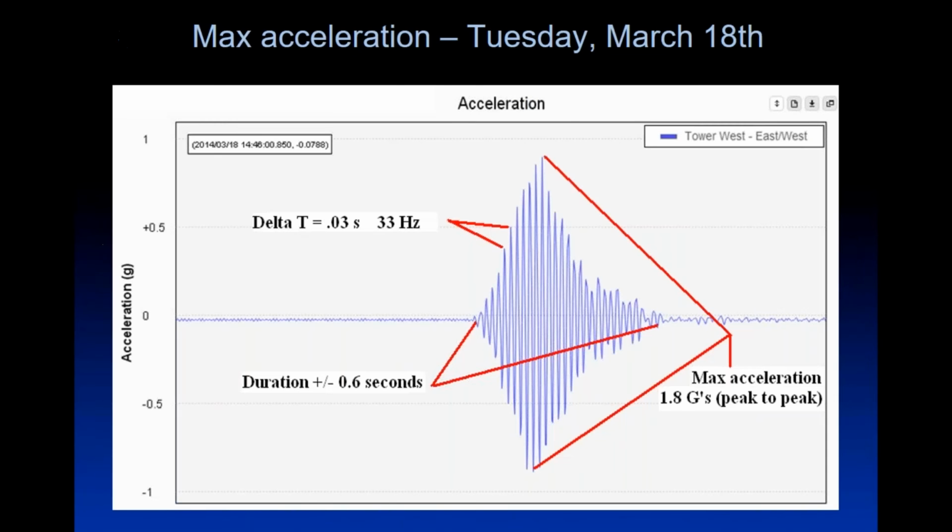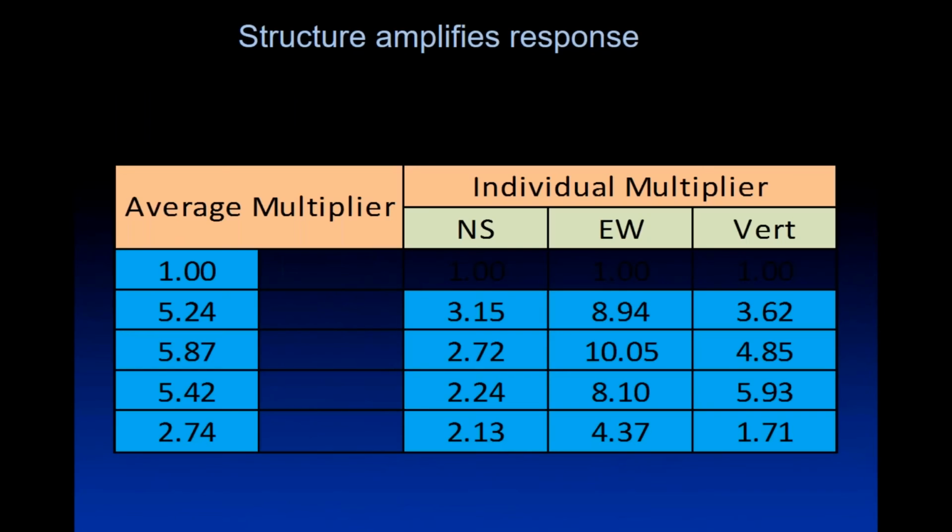This is the building that I'm talking about. The measurements using the conventional means were taken down here. We measured down there as well, but we also measured up at the top of the transepts and the nave and in the bell tower. These criteria say that that dynamic magnification factor will be a maximum of 4 in any structure, despite the fact that the experiments that produced these values were conducted in the 1970s with the equipment that was available and at frequencies that don't apply to structures such as this.